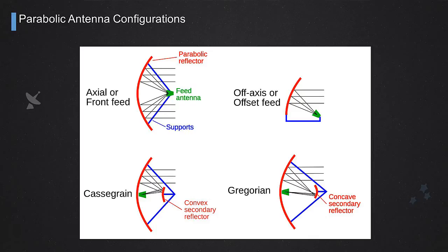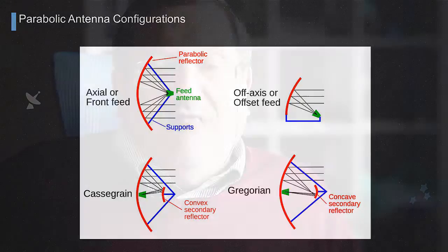You have your parabolic reflector as in the configuration shown before, and then you have a horn, a feed, that is the receiving feed that is put in the focus of the configuration. All rays are reflected by the parabolic surface and concentrated into the feed antenna. Of course, what counts is the area of the parabolic reflector, so the effective aperture of the antenna will depend on the size of the parabolic reflector. That is the one that we will use to calculate directivity.